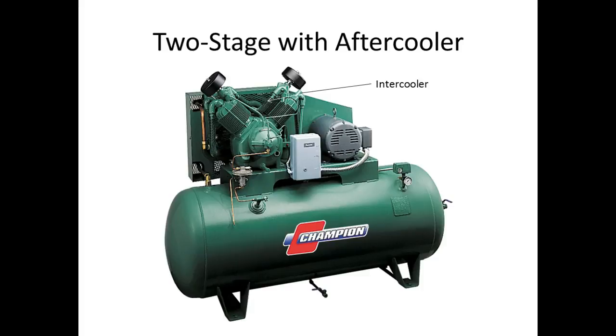Now, if we looked at these and the cylinders were the same size, they're not using it to increase pressure, they're using it to increase flow. But if you look at them and they're different sizes, they're not increasing flow, they're increasing pressure. So what they're doing is they're taking something that's already pressurized and they want to pressurize it more. So you're not going to feed it into a cylinder that's the same size, because as soon as you did, it was uncompressed, right?